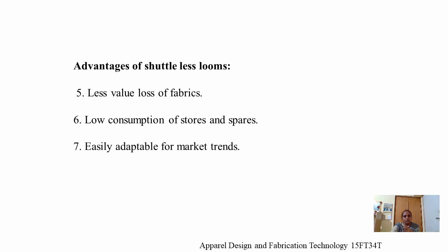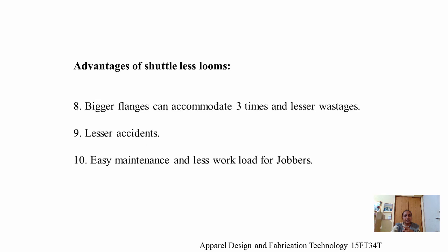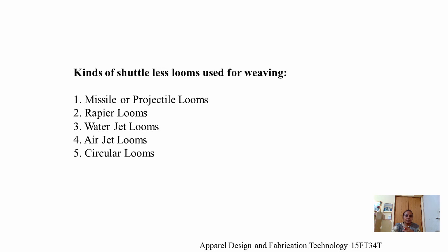Less value loss of fabrics, low consumption of stores and spares, easily adaptable for market trends. So these are the advantages. Bigger flanges can accommodate three times more yarn and give lesser wastage. So wastage will be less compared to the shuttle loom. Lesser accidents, easy maintenance, and less workload for the jobbers. So it is very simple.